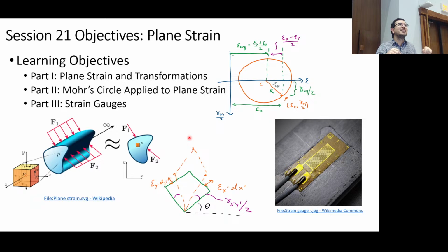It was a beam, and we applied a load over here, so it was putting the strain gauge at the top in tension and the bottom in compression. Excellent, so now we've got it. Was this three-point bending? In other words, did you have essentially a pin on the side and a load cell in the middle, pushing down? Clamp on one side. Okay, so it was a cantilevered beam.